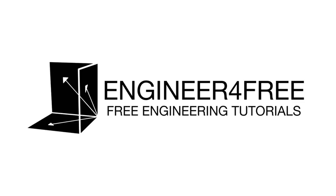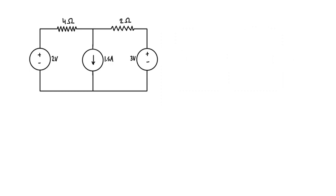So in this video, I'm going to explain what supermesh analysis is, how we can use it, and we're going to go through this example where we find the currents flowing through each of these resistors at the top using supermesh analysis. Now, supermesh analysis is basically mesh analysis, but it's what we have to do if we have a current source that's between two meshes or two loops.